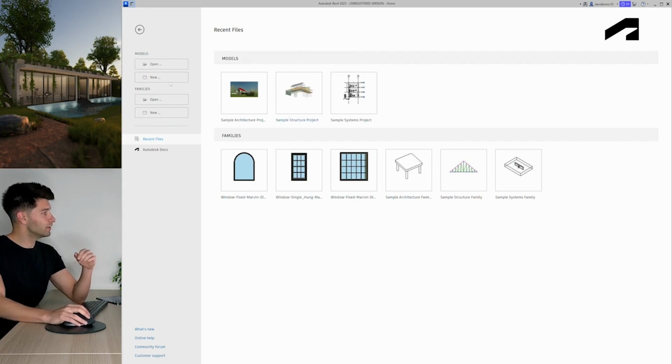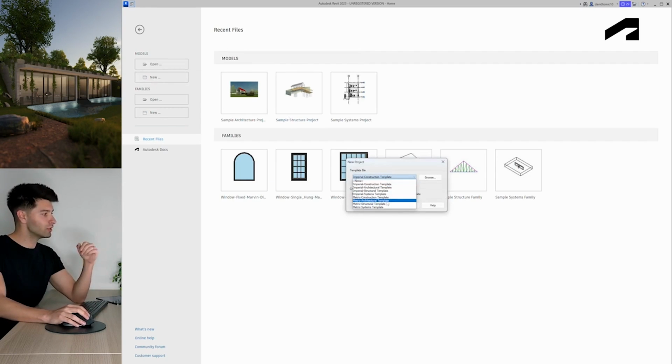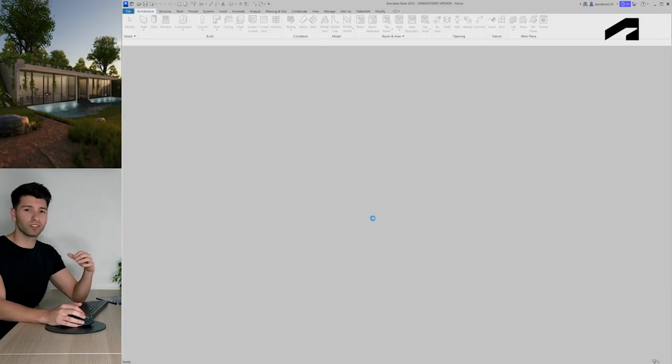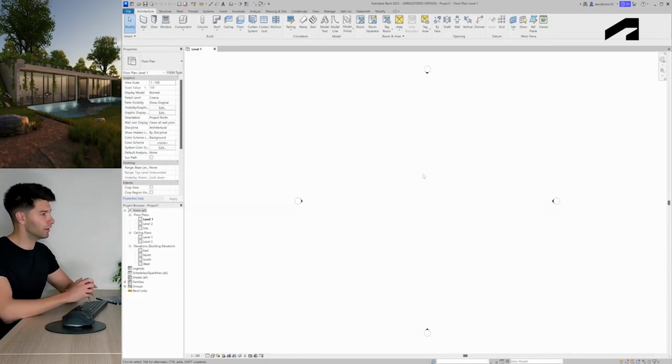We're going to start today's video by going into new Revit file and we're going to select a metric architectural template. For me, it's metric because I'm in Australia. For you, it can be imperial. It's completely up to you guys. Next, we're simply going to dive in and press OK. Find ourselves immersed in the Revit environment.